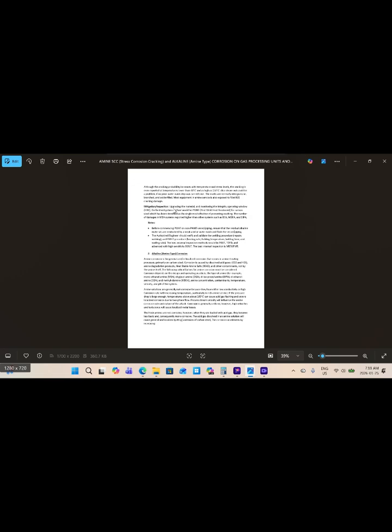For mitigation and inspection, we can detect this type of damage by upgrading the material and monitoring the integrity operating window, IOW, by avoiding this threshold temperature range. One of the best mitigations is to implement post-weld heat treatment on the welding of carbon steel material to reduce the stress remaining on the weld lines.